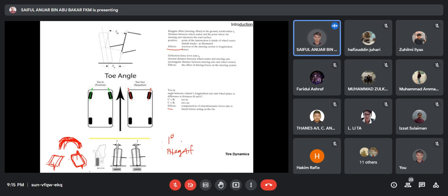Including me. So for me, I already changed the rear lower arm using an adjustable lower arm from the aftermarket, so I can adjust the camber angle myself at the workshop. But if you don't change to an aftermarket adjustable lower arm, then you cannot do anything because the camber angle is fixed by the manufacturer.